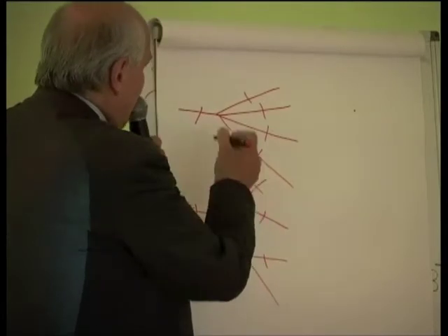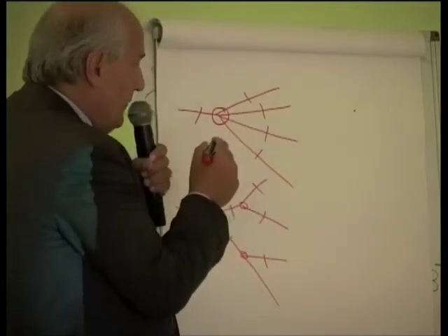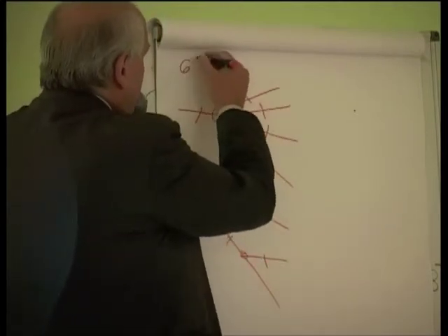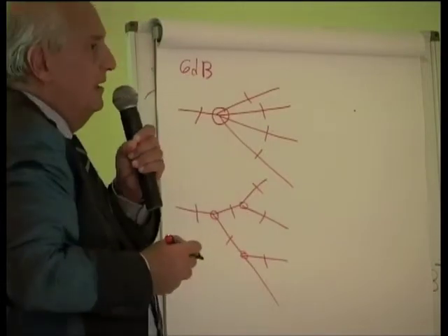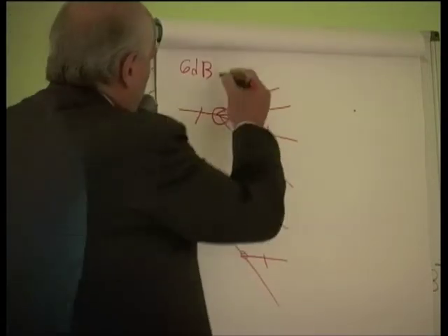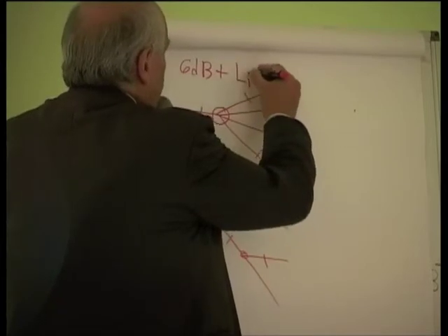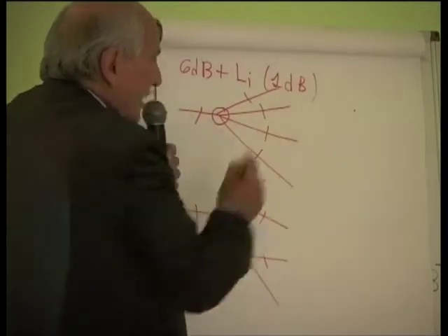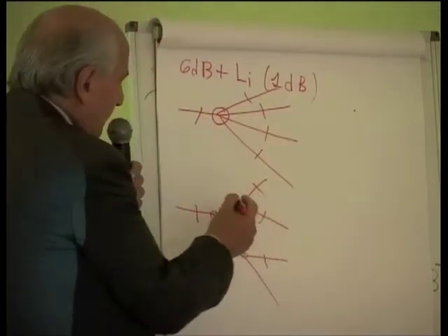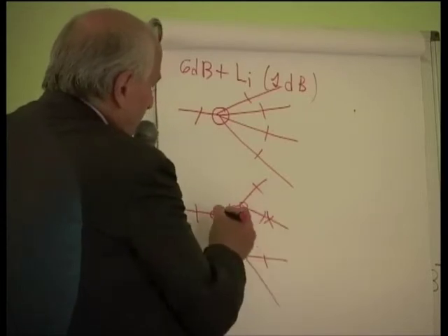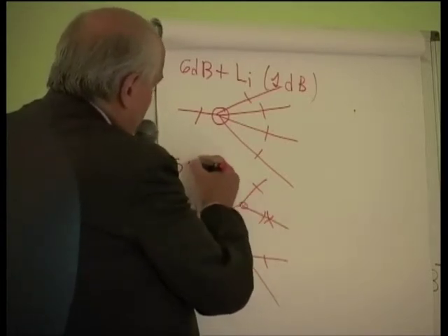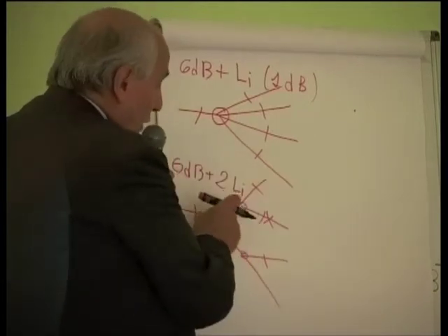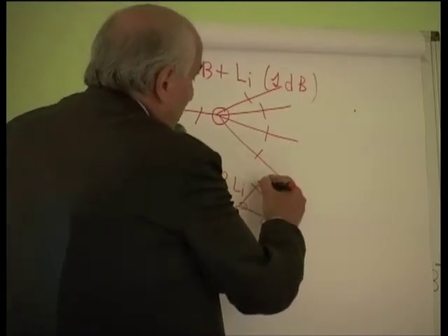recall the fact that the attenuation here is given by this being 4 times, which is 6 dB of theoretical attenuation plus the insertion loss, which could be, for example, 1 dB for a splitter of this size. If you go here, the loss is 2 times 6 dB plus 2 times insertion loss, because you have 2 splitters, and this could be 2 dB.